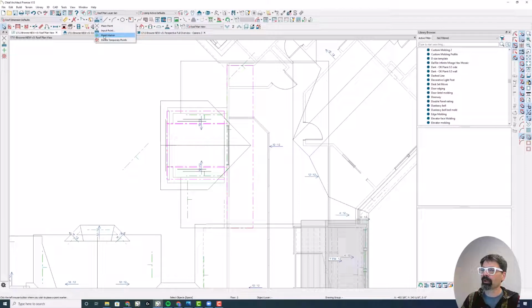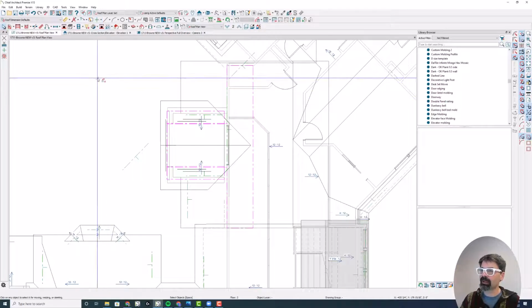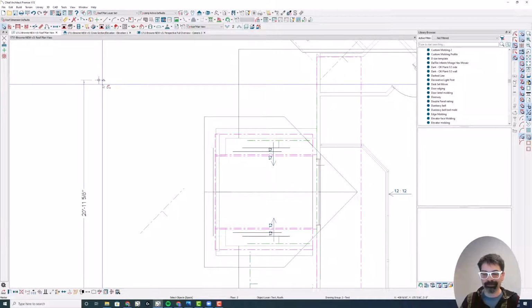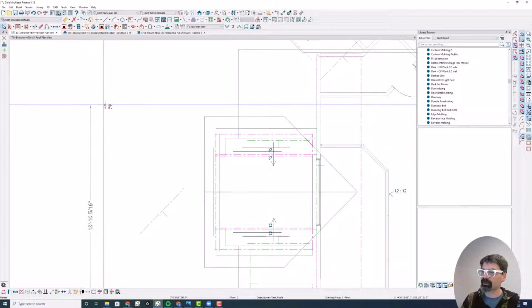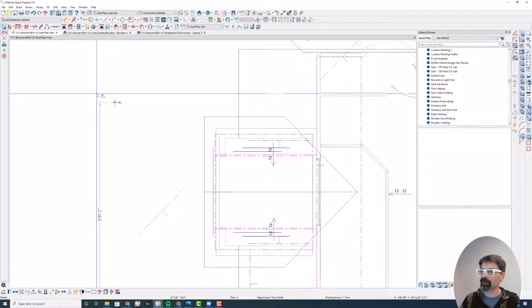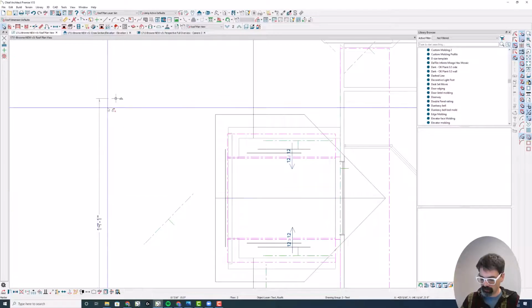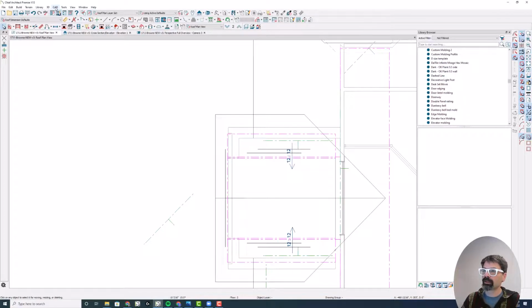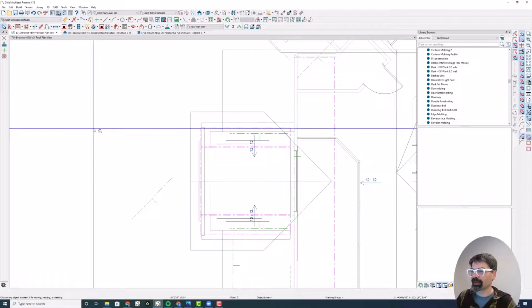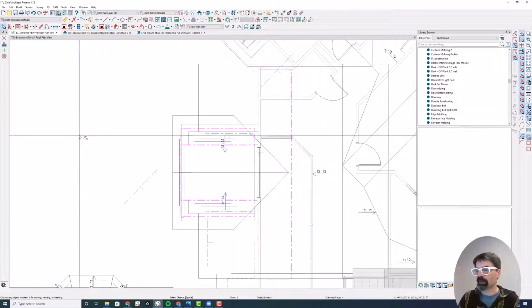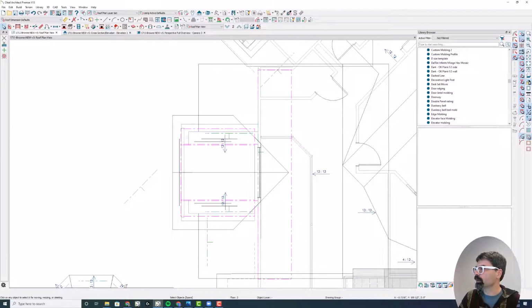You can put a point marker. This is a different place point. That's a temporary point. This point marker is an actual object, it's not CAD, it's some sort of object that you can select, you can move, and you can dimension to it, as you see with that temporary dimension.